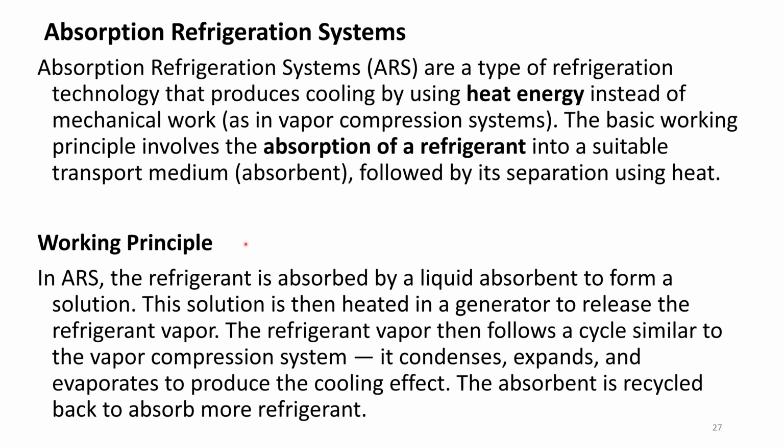So the working principle is: the refrigerant is absorbed by a liquid absorbent to form a solution. This solution is then heated in a generator to release the refrigerant vapor. The refrigerant vapor then follows a cycle similar to the vapor compression system. It condenses, expands, and evaporates to produce the cooling effect. The absorbent is recycled back to absorb more refrigerant.